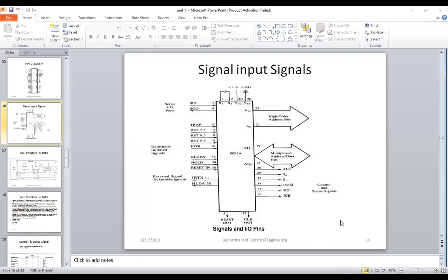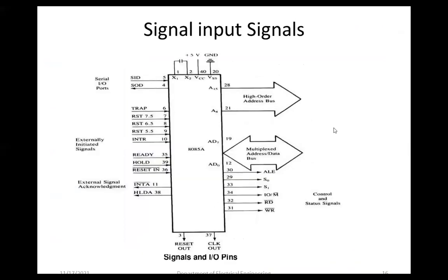See, in your 8085, we discussed in the previous two lectures, here are the interrupts: one, two, three, four, five. There is no priority register here, and there is no enable register here. Here we have to use these interrupts directly.